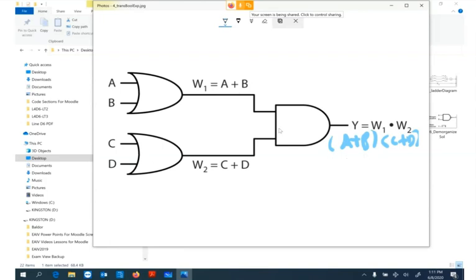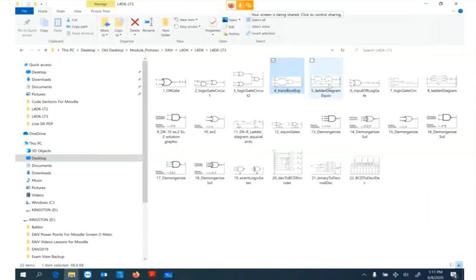Now, when you look at that equation and the equivalent in switches, the switches make a whole lot more sense for me. If you think of our original OR instruction as having 2 switches in parallel, basically we have 4 switches total, 2 switches in parallel here, 2 switches in parallel here, but in series to satisfy the AND. So they do show that here.